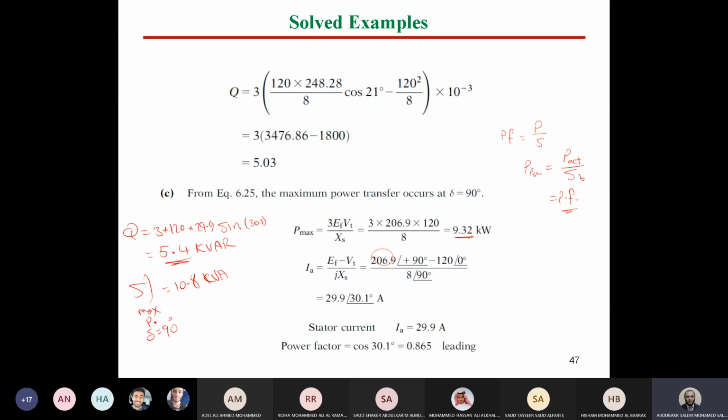Okay, and we said before, overload is allowed for certain periods. Overload for how many percent? 10%, 20%, a certain value, according to the time as well. For instance, we can have 10% overload for 1 hour, 20% for instance for 40 minutes. However, 200 or 100% extra load cannot be achieved even for a very small time. Okay? It's not allowed.